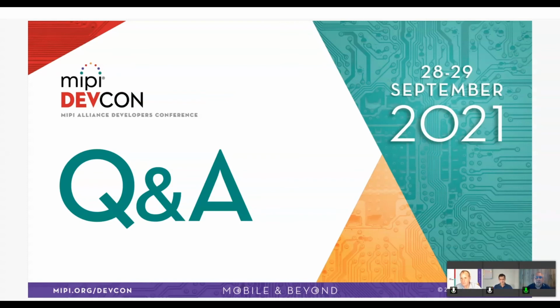So I think that as usual, it's important what the use case is. Depending on your required bandwidth and simplicity, this is a user decision that needs to be made. Of course, there is a main difference between A-PHY when comparing to C-PHY and D-PHY, which is the long reach support. So I think that the main discussion would be between C-PHY and D-PHY. And as usual, this depends on the use case and the expected performance.